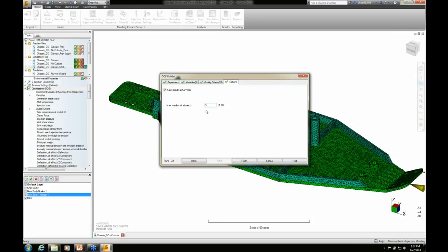I've seen a couple of times in the DOE where we maybe vary the melt temperature, the mold temperature, or the injection speed, and it will yield a short shot. Well, inside of our DOE software, that's unacceptable. But rather than just saying, hey, this creates a short shot and it's totally unacceptable, we try to redefine that window, basically constrain it a little bit tighter, and see if there are some variables in there in order to actually test the variation that we've got while still producing a good part.